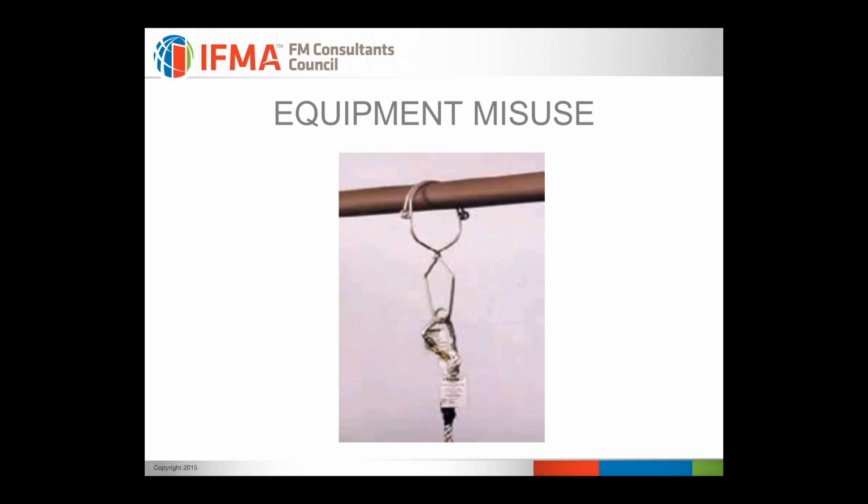But really beyond that, our philosophy towards fall protection and safety is, OSHA, yes, that's the law. You have to do at least what it says, but it's really the bare minimum. A lot of people have been hurt or killed even though they were complying with the regulation. So we think it's not that much more difficult to go above and beyond OSHA, and following the ANSI Z359 standards is a good place to start for more information. But let me share some other reasons why PPE is maybe not the answer that a lot of people think it is.